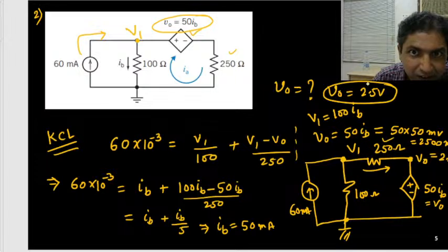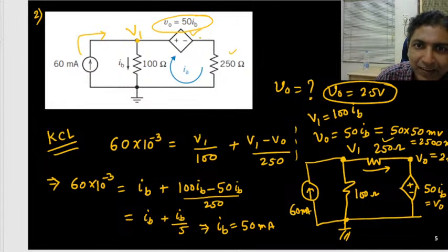So you can check. If a circuit contains some dependent source, you need to understand which method you will be using. This is a simple circuit. As it is having a single node, we can go for node analysis. We can use other things. We can use source conversion again. This right side voltage source and resistance we can convert to current source, but be careful, there we can have a controlled current source.